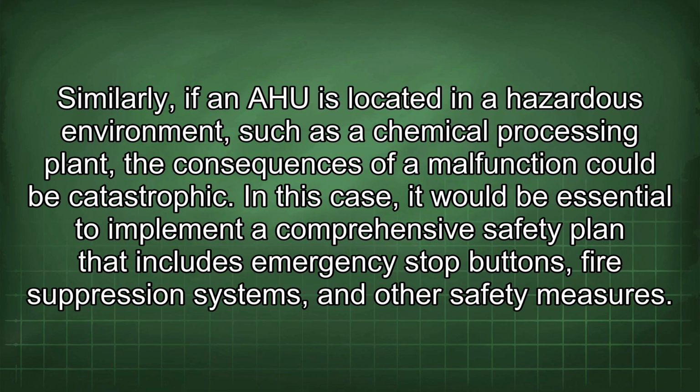Similarly, if an AHU is located in a hazardous environment, such as a chemical processing plant, the consequences of a malfunction could be catastrophic. In this case, it would be essential to implement a comprehensive safety plan that includes emergency stop buttons, fire suppression systems, and other safety measures.